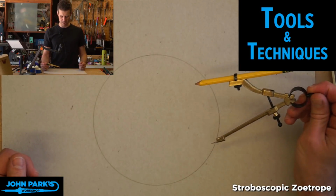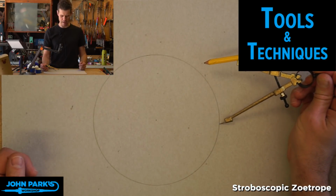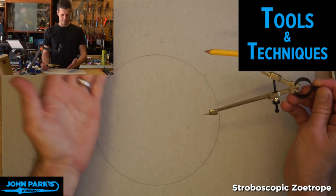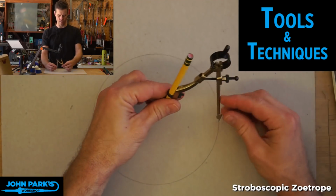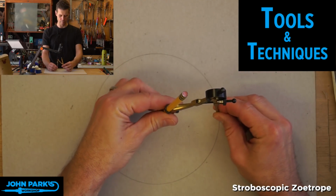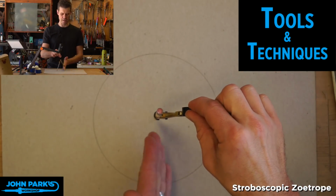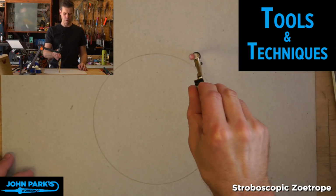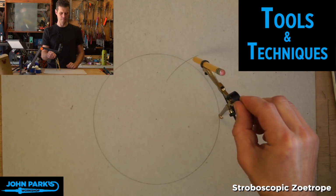So now what we can do to create 6 segments on here is take the point of the compass, and I'm going to set it on the circle anywhere on the perimeter of the circle. It doesn't really matter. So you don't have to do any measurement in particular to get it into a nice place. I'm going to place it kind of over here on the right, but it actually doesn't matter one bit. So by placing this compass here, and it still has the radius of the circle, all I need to do is create a mark right here.